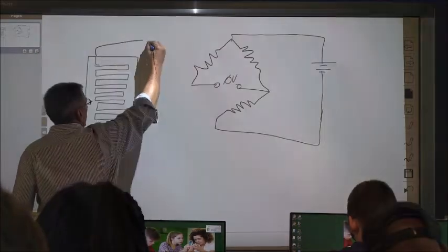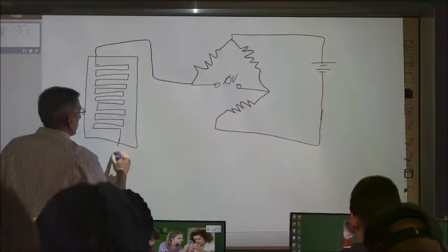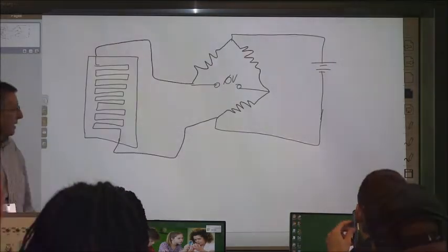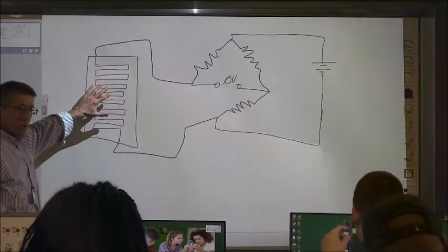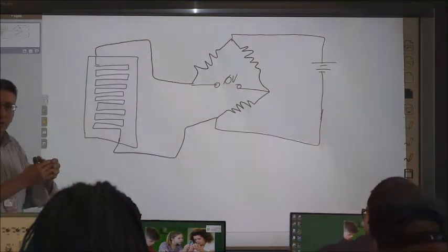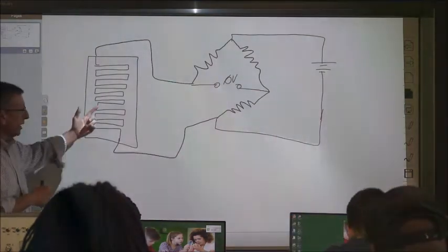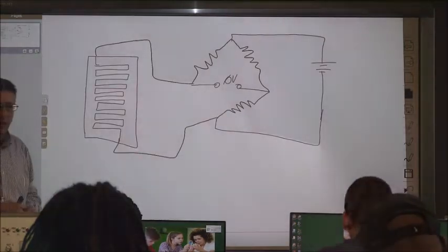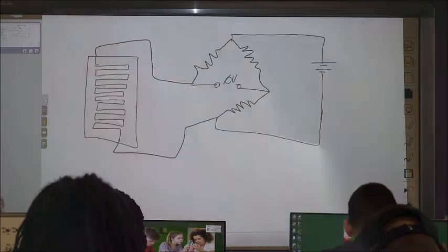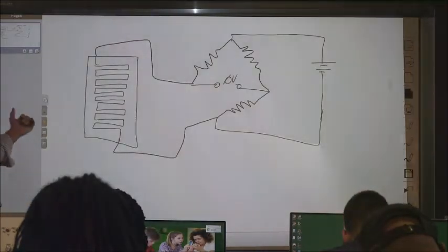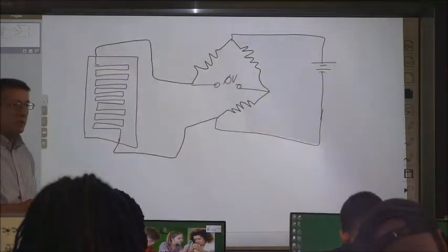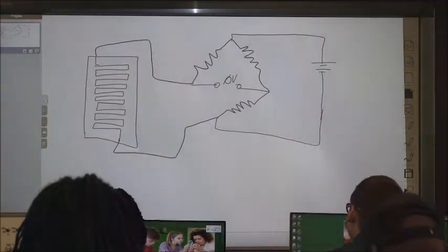So what we do is we replace one of the resistors with a strain gauge. And the way the resistance changes on this thing is it flexes. As it flexes, the resistance changes in this copper trace. You see a lot in like research and development stuff. We used to use it a lot in engine testing, engine research, and that type of stuff. It's testing physical load.